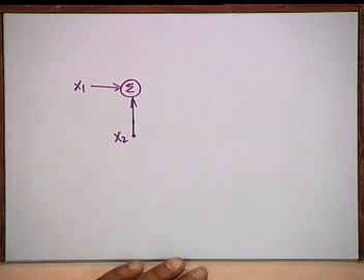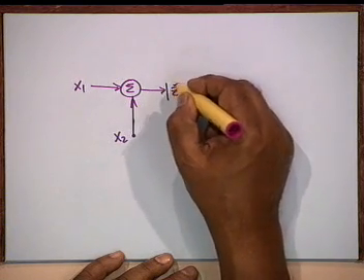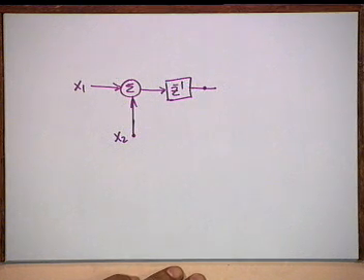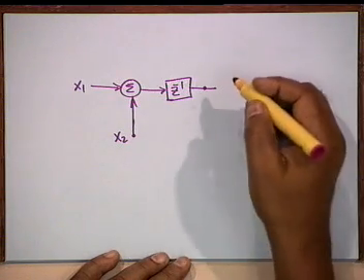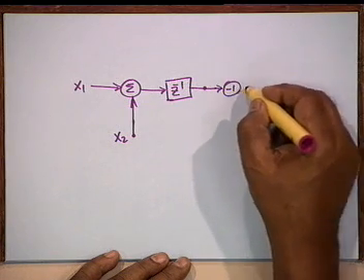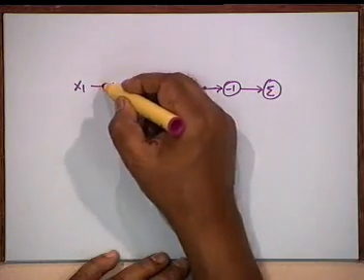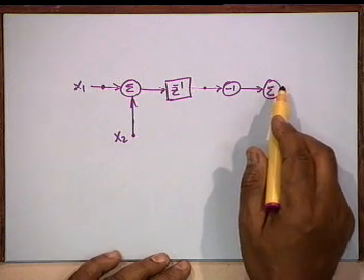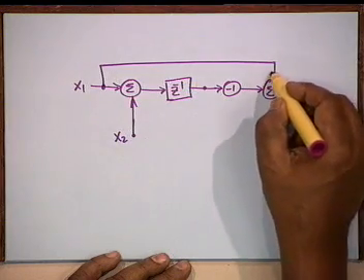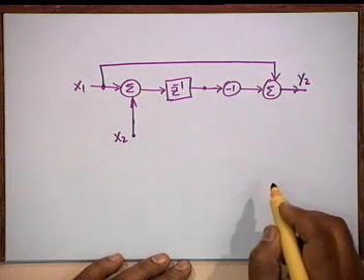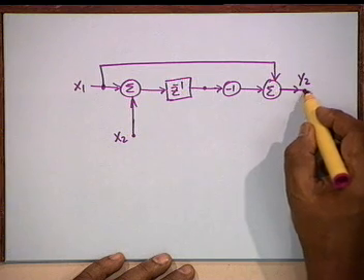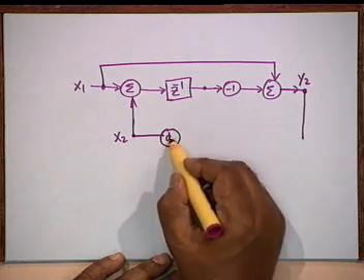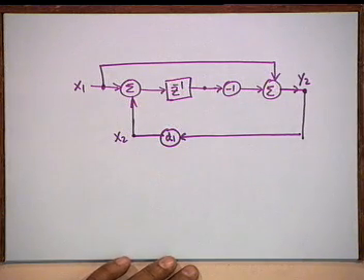First we add x1 and x2 because this is what we require, then we delay by one sample. So, I have gotten the term z inverse (x1 plus x2). I have to multiply this by minus 1 and then add to x1 to get y2, and I know y2 and x2 are related by the multiplier d1. So, I use a multiplier d1 to construct x2.